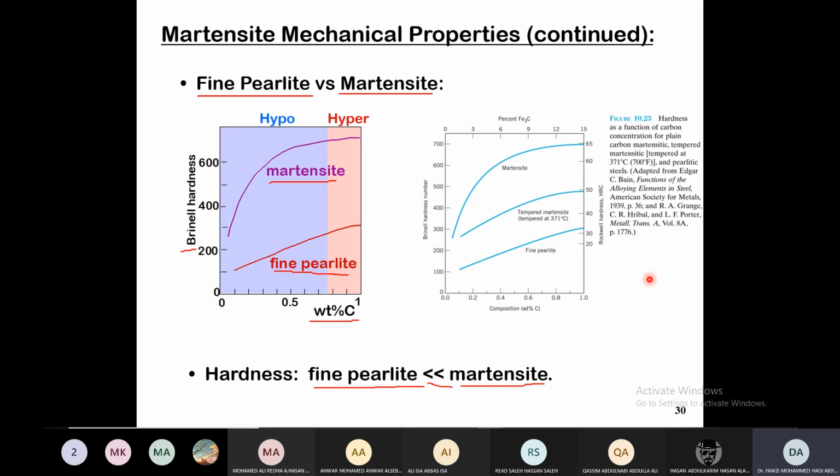What is tempered martensite? Well, basically, the martensite itself as a 100% phase is not actually usable because it has negligible ductility. Forming of that material is very difficult. It has that brittleness, and that makes the material non-usable in practice. So that's why we do something called tempering of martensite in order to make it less brittle and more ductile with high strength, which gives some application to this martensitic structure.